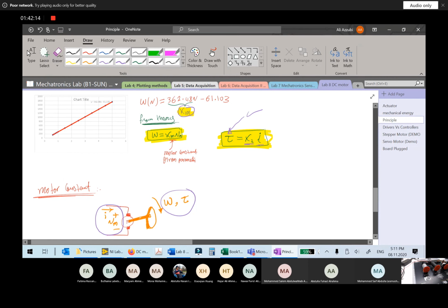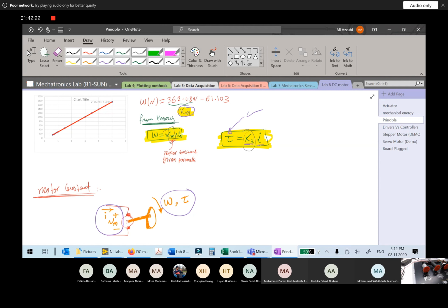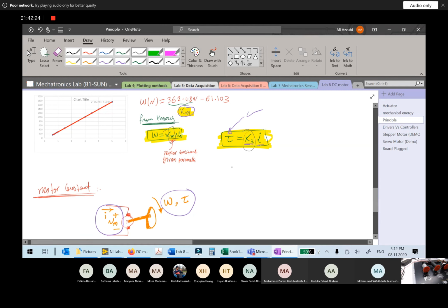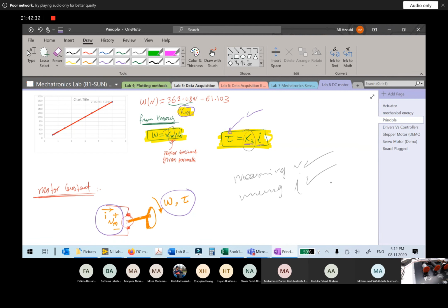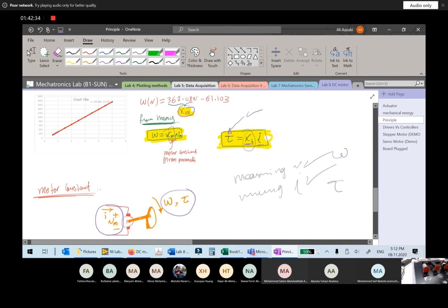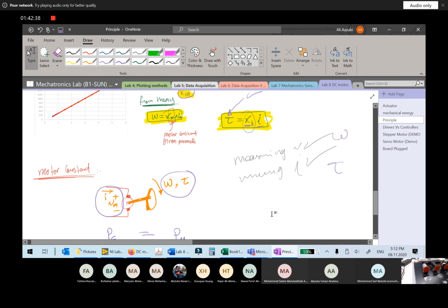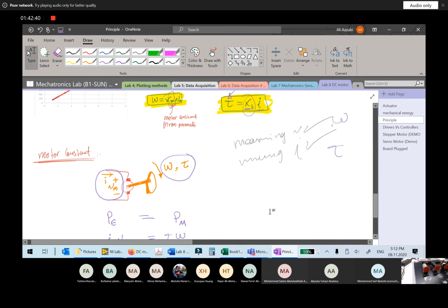So this way we have actually nailed this DC motor. It's just by finding this constant. Give me the constant and I'll tell you, by measuring V or I, we know how to measure V using a DAC or measuring I using a DAC. Simply I can find my torque and omega. Measure them or control them. Kushab, you agree about this point? You all understand?